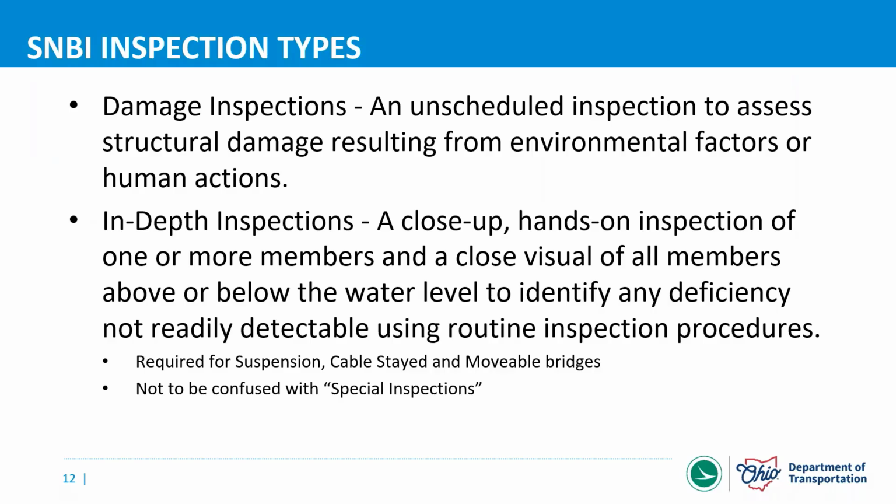But if you have in-depth or complex inspections on suspension, cable-stayed, movable bridges, maybe post-tensioned bridges, things that are different or unique from our typical bridges, we want that inspection type coded as in-depth. If you are doing a more close-up or specialized inspection on those special parts of the bridge, we want that again coded as in-depth, not as special going forward.